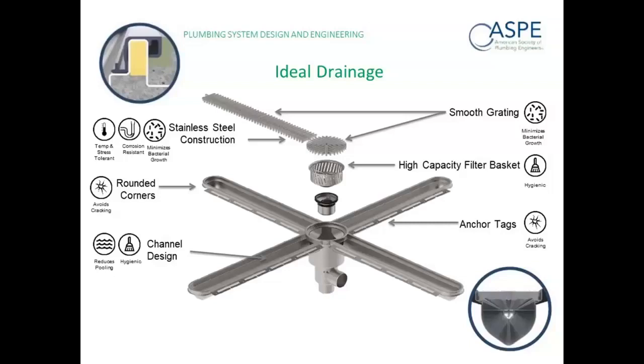That's true, correct? Almost every installation where we're doing a floor where they ask it be done in the field to fill that shoulder, which is evident in that top left picture with the yellow, that never happens. Maybe 1 in 10 you see a plumber actually doing it. But if it isn't done, that shoulder will eventually crush or cavitate, thereby leaving a void against the floor system. And we get calls all the time, oh, your floor is failing at the drain.